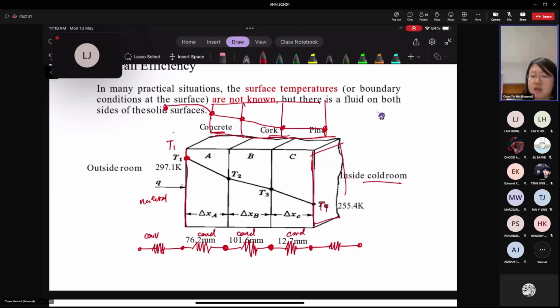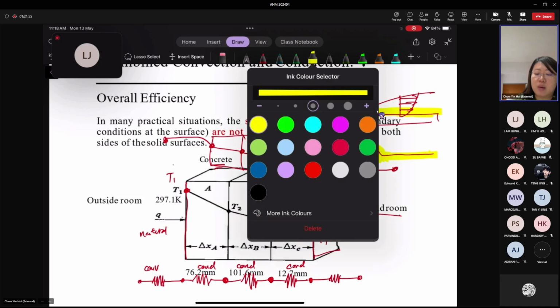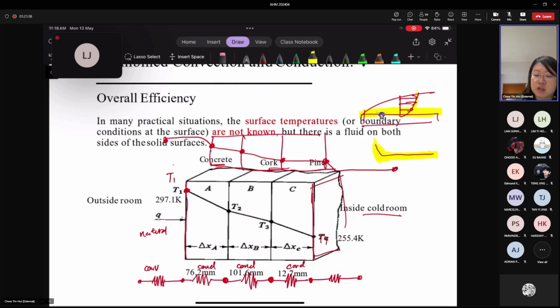For convection, the temperature drop is usually drawn in this manner because of the velocity boundary layer and the temperature boundary layer. In the section closer to the plate, heat is mostly conducted by conduction. That's where you have the most variation in temperature, this section here, that's why you see a drop. Further from there it's a flat line, because that's where most of the heat is transferred by convection, due to a lot of eddies.